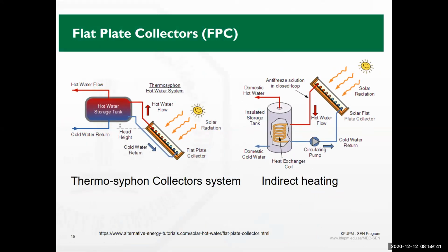These are layouts of flat plate collector connected to storage. And the figure in the left is interesting because it is considering the effect of buoyancy. When you look at it, there's no pump in the system. What you are doing, you have a solar collector, and the solar collector here is heating the water.